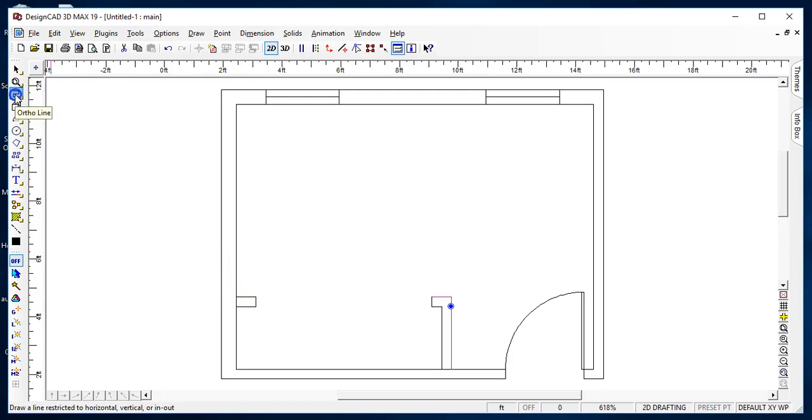We'll take and draw this using this first tool. This is my line drawing tool, but it's good for drawing angles. I want to draw a bifold right here from this point, so I snap to this point, and I want to go up 45 degrees.